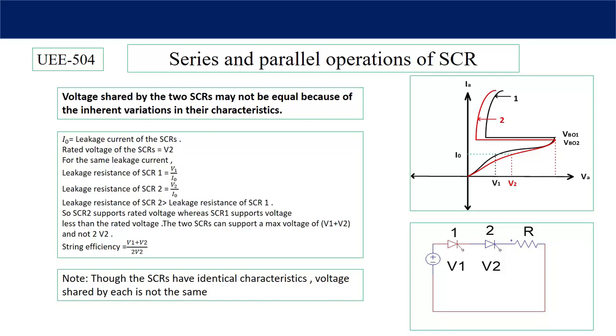Then the resistance offered by the equivalent combination of thyristor and resistance of the individual thyristors will be equal. Then the voltage shared will be equal. But this system becomes too complex if the number of SCRs in the system is large, because these resistances are to be found out individually.